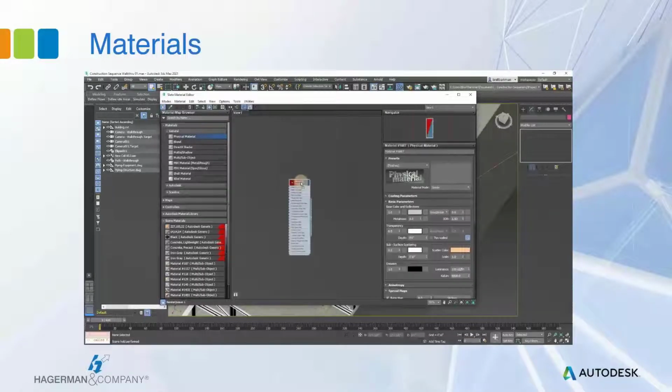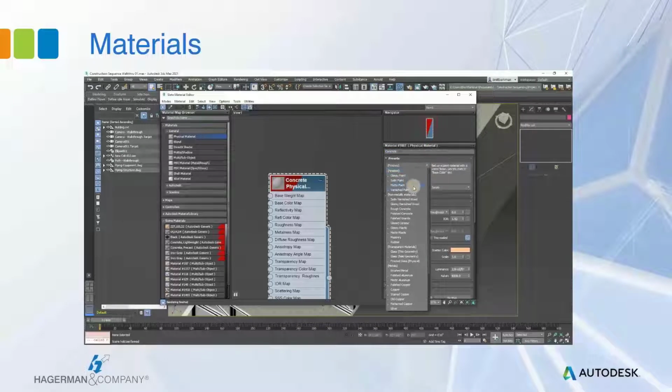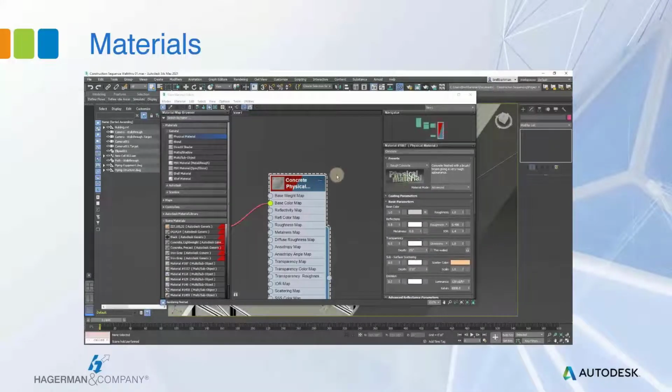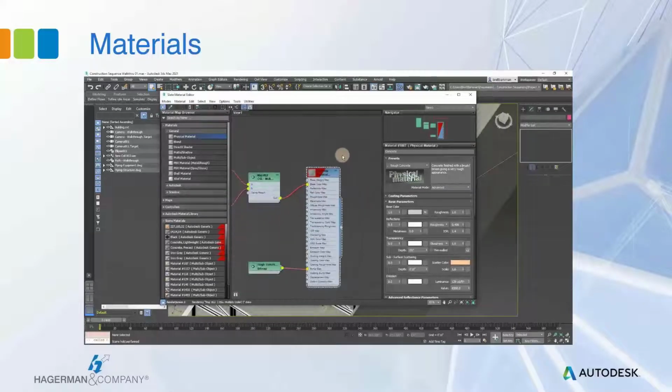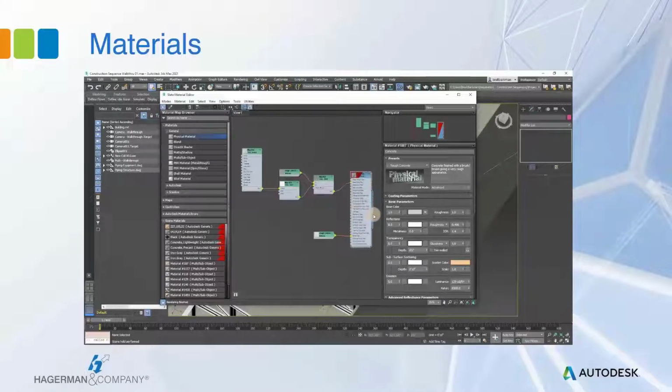I'm going to use a physical material here, so I'll drag one onto the canvas here in the material editor. We'll give it a name. And then I'm going to use one of the presets. It's a nice thing about the physical material in 3ds Max. We can use a preset and let Max do the heavy lifting. Once you have your material created, then we will assign it to objects that we select in the model.